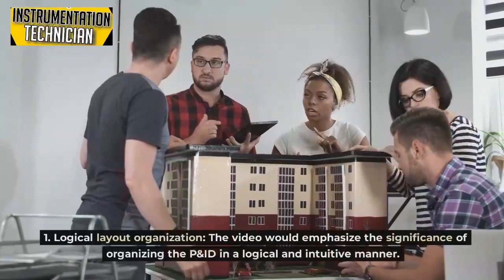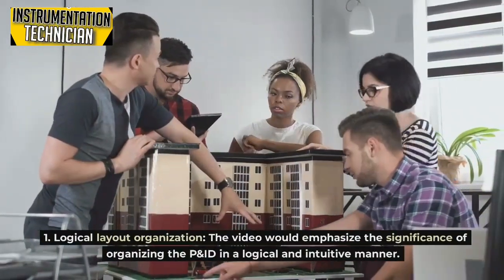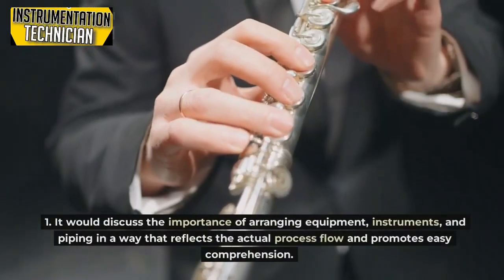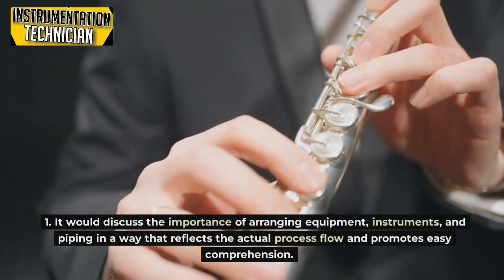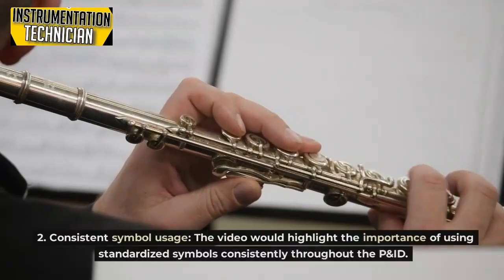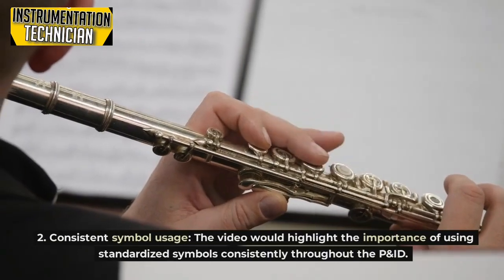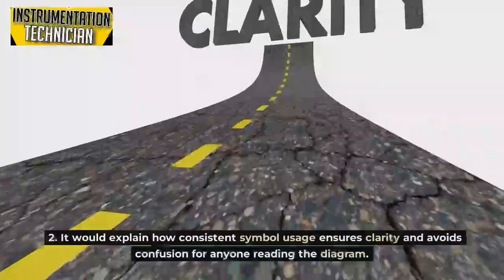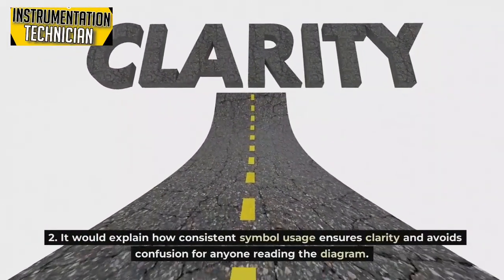1. Logical layout organization. The video would emphasize the significance of organizing the P&ID in a logical and intuitive manner. It would discuss the importance of arranging equipment, instruments, and piping in a way that reflects the actual process flow and promotes easy comprehension. 2. Consistent symbol usage. The video would highlight the importance of using standardized symbols consistently throughout the P&ID. It would explain how consistent symbol usage ensures clarity and avoids confusion for anyone reading the diagram.